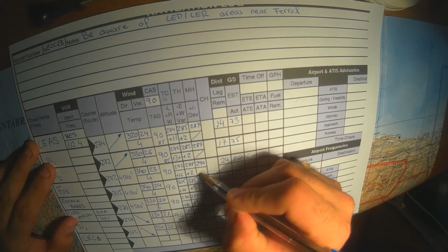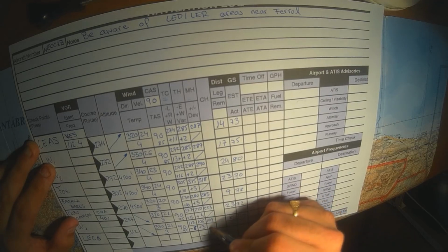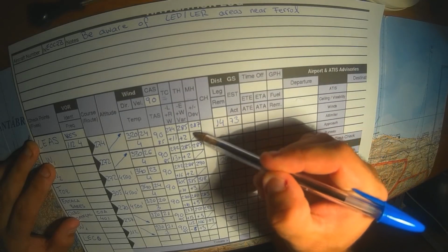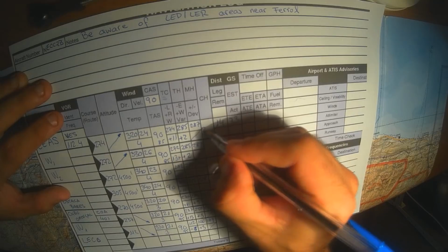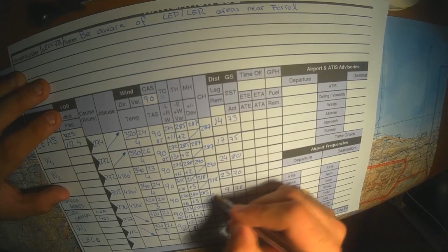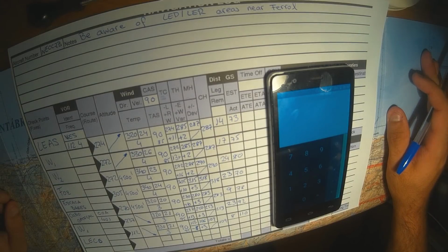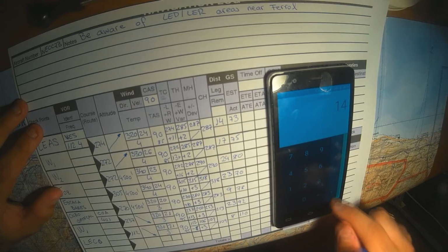Compass deviation rarely exceeds 3 or 4 degrees, so we'll take compass heading equal to magnetic heading. Our legs are not longer than 30 miles, so that error would be negligible. We will now calculate the total distance of our flight by just adding all the partial distances that we previously measured with the plotter instrument.